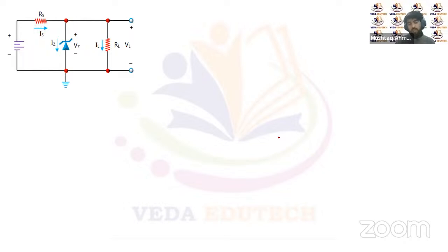The voltage across the Zener diode is always constant in the on state. Here you can see this is the symbol of the Zener diode, in the reverse bias condition. VZ we call the Zener breakdown voltage of the Zener diode, and IZ is the current flowing through the Zener diode. So this Zener breakdown voltage will be constant here. Because of the fixed nature of the Zener diode, it works as a voltage regulator.